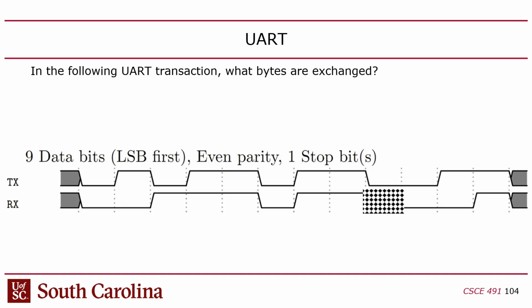So every single time you send anything, you have to put the start, stop, and optionally the parity around it. Does that make sense? You pay the protocol overhead individually for each word you send, which is another weakness of UART. You would think it would have some way to batch together multiple words in order to minimize the overhead, but it doesn't.